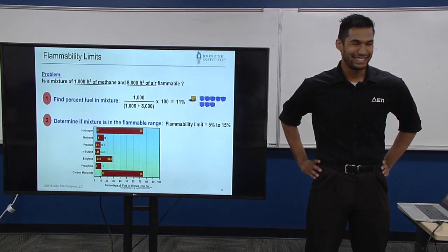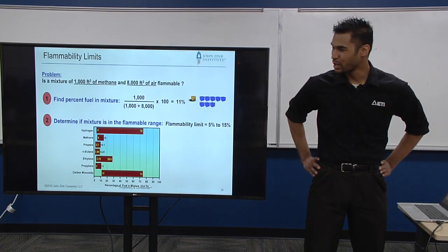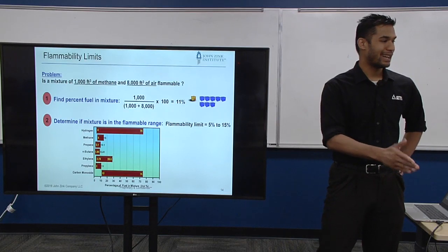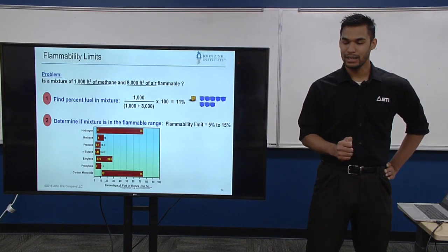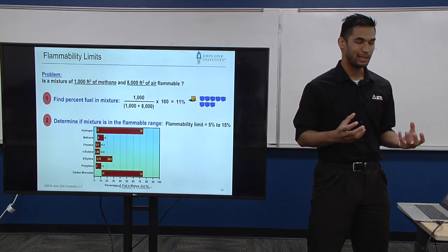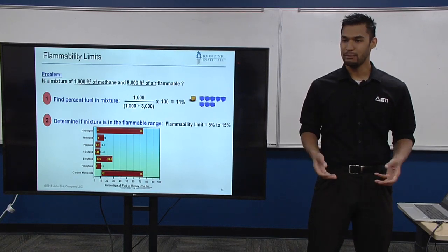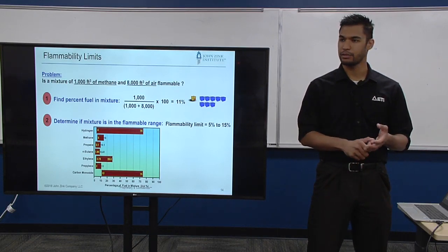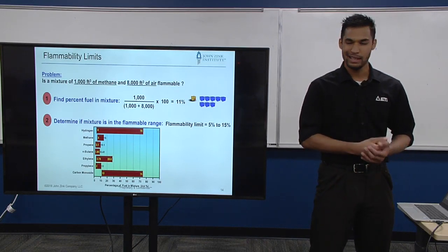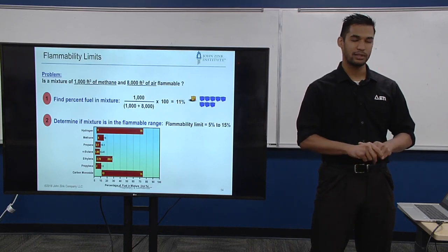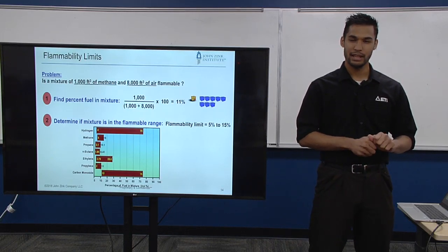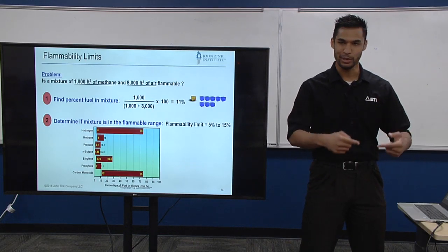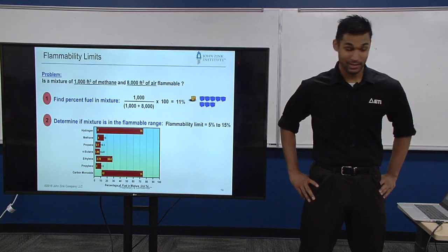It's important to understand that different fuels have different properties. And if you have a mixture of fuels, let's say 50% hydrogen and 50% methane, you can't just average the flammability limits. There are mixing rules based on Le Chatelier's principle, and they're in your combustion book. I think everyone's getting a copy of the combustion book. I like to put one of those questions on the first test, but it's pretty straightforward. You go to about page 75 in your book and follow the directions. But just a heads up.